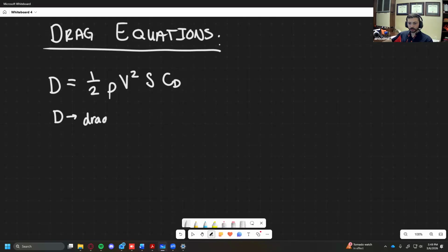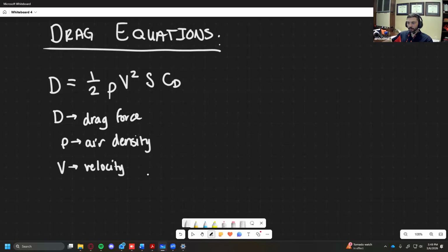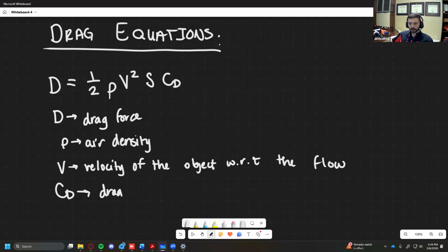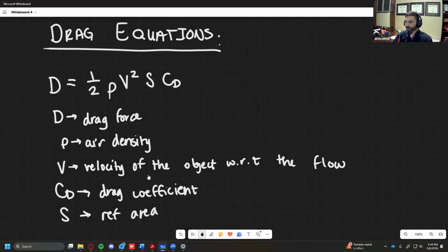But just to go over it, D, this is your drag force. Okay. Rho is going to be your air density or the density of whatever the fluid is. In this case, it's air. V is going to be your velocity of the object with respect to the flow. And that's kind of an important thing. CD is going to be your drag coefficient. And S is going to be your reference area. Okay.